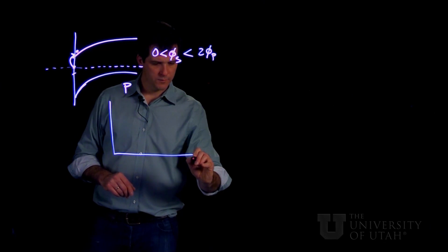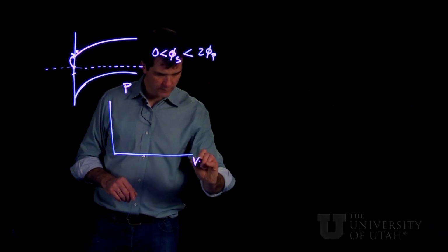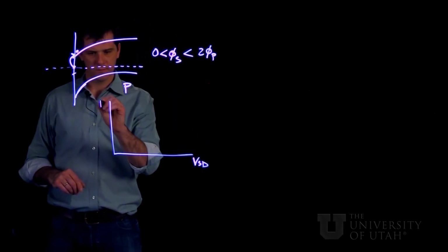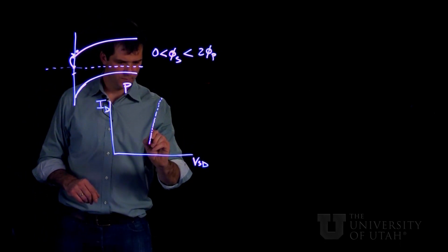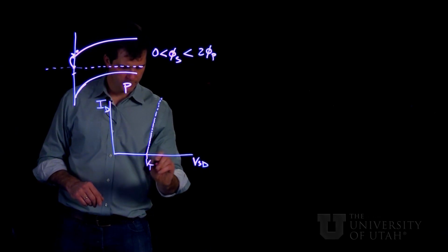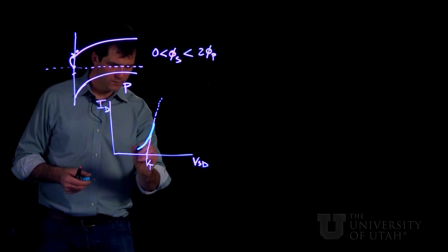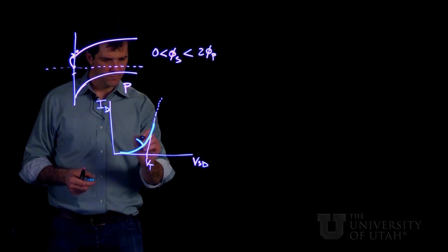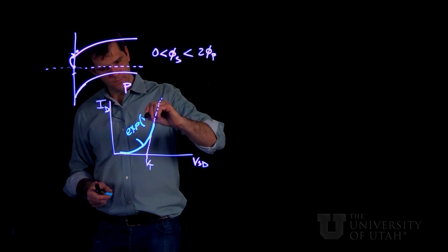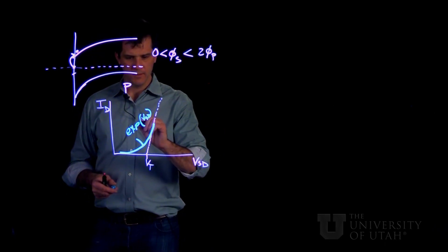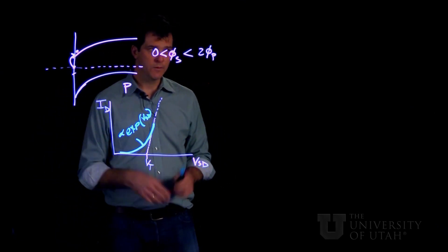So this is going to mean that there's some conductivity in the channel. If we draw out our ideal V source drain versus I drain, we would predict this curve intersecting at V threshold. And in reality, we're going to see the onset of current, which is exponentially dependent on the source drain voltage below threshold. So why does this happen?